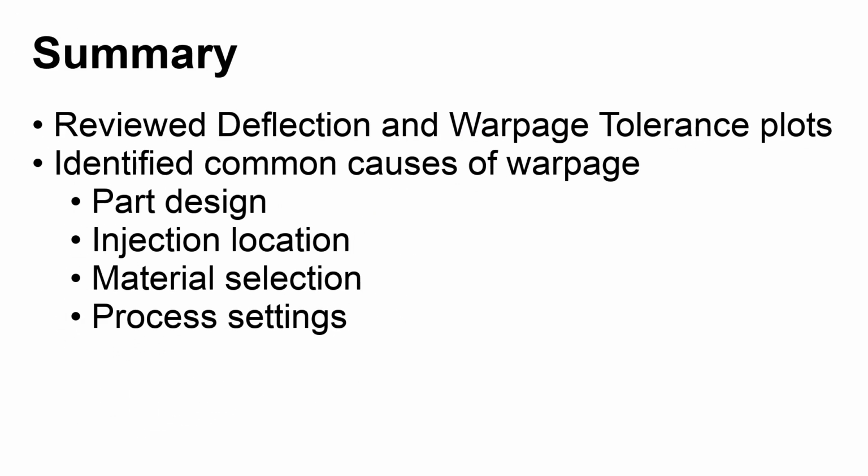In this lesson, we reviewed both the deflection and warpage tolerance plots. We identified common causes of warpage and discussed ways to minimize or reduce it by altering the part design, injection location, material selection, and process settings.